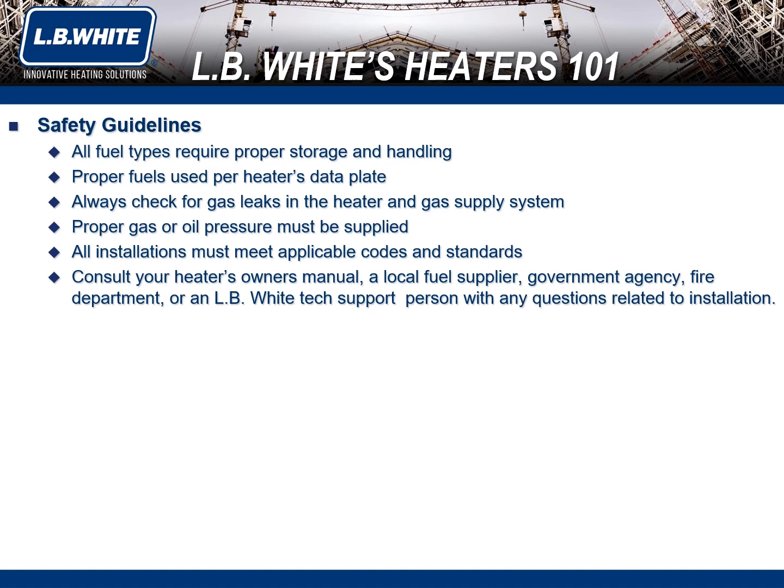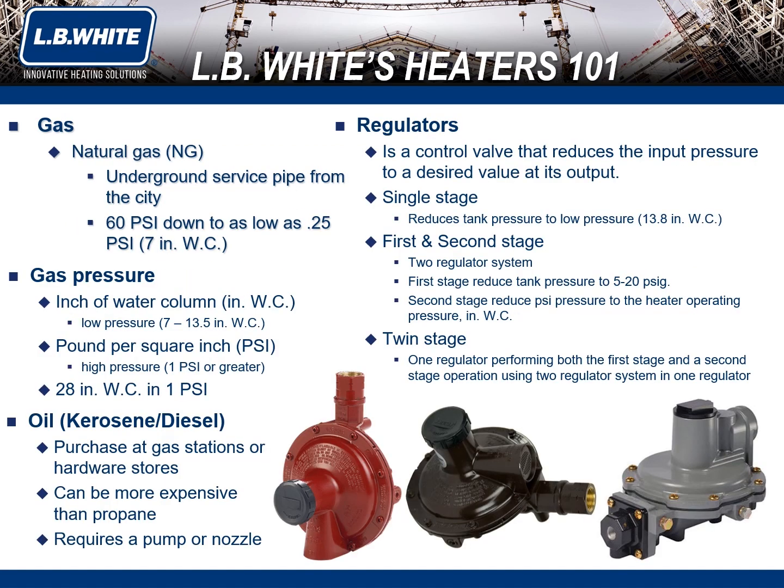Back to regulators. There are different types of regulators. Single stage. This regulator reduces the tank pressure to low pressure. First and second stage regulators. This involves a two-regulator system. The first stage regulator reduces the tank pressure down to 5 to 20 psi. The second stage reduces this pressure to the heater operating pressure, inches water column. And lastly, twin stage regulators. This involves one regulator performing both the first and second stages of operation using a two-regulator system in one regulator.